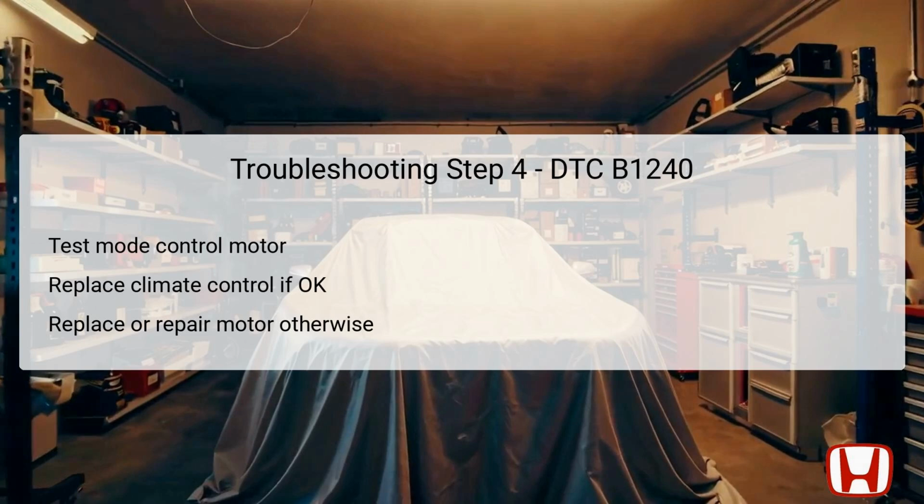Conversely, if the mode control motor fails the test, the appropriate course of action is to either replace the motor or address issues related to the mode control linkage and doors that could compromise proper operation. This step effectively determines whether the issue lies with the motor or the supporting components linked to its functionality. Ensuring precise diagnostics at this stage is crucial for successful resolution.